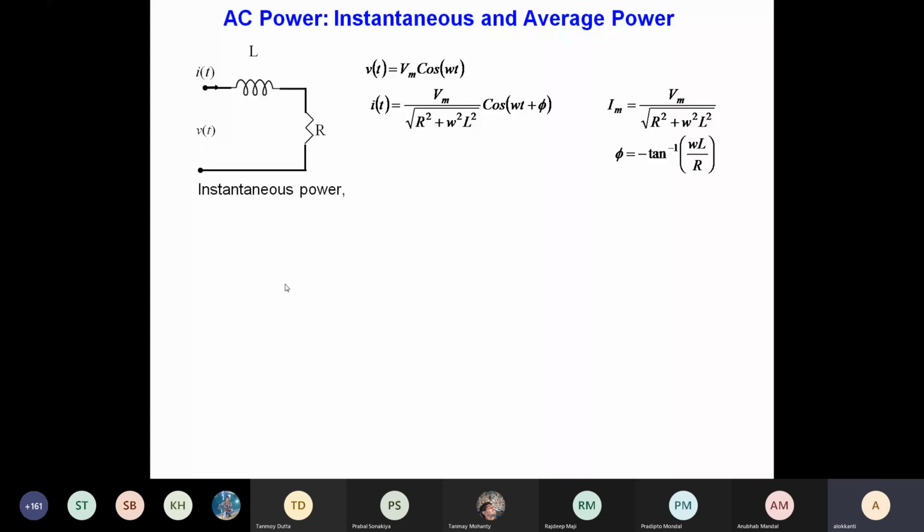Voltage and current will have different magnitudes, but the nature is basically sinusoidal. And at every t there is a V(t) and there is an I(t). So at every instant we can actually find out what the power is. Voltage is V(t) and the corresponding current is I(t). Then the power at that instant, P(t), is given by V(t) times I(t).